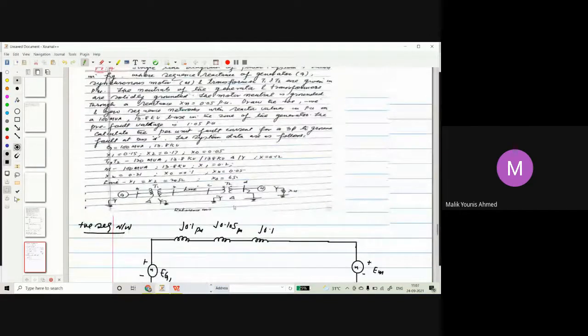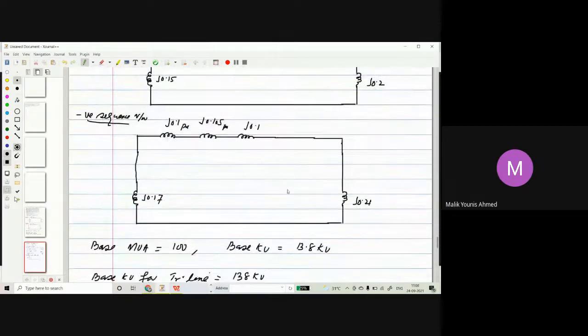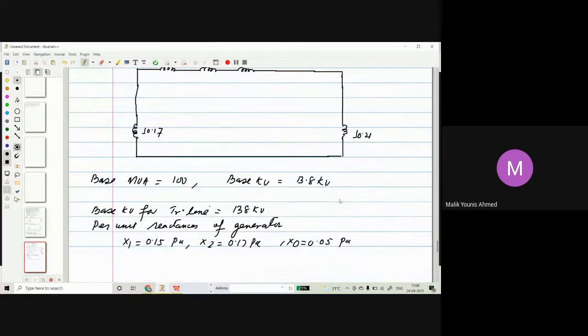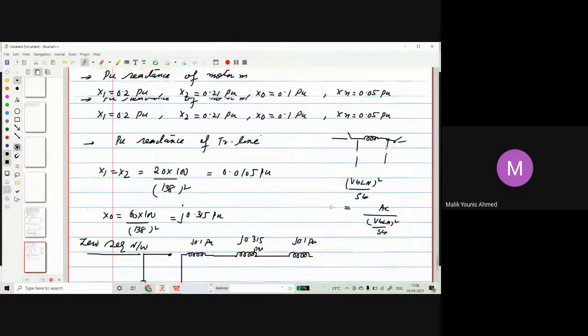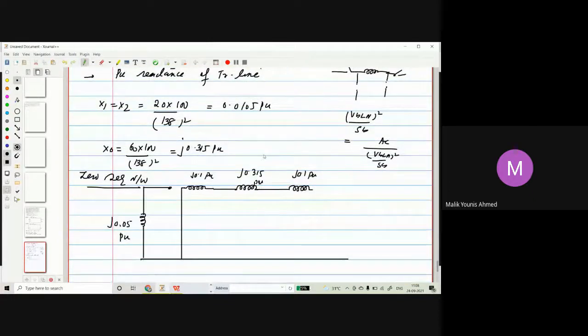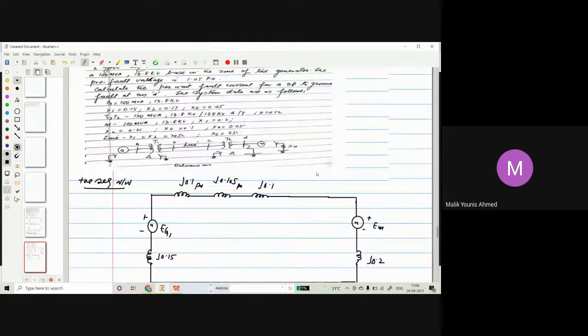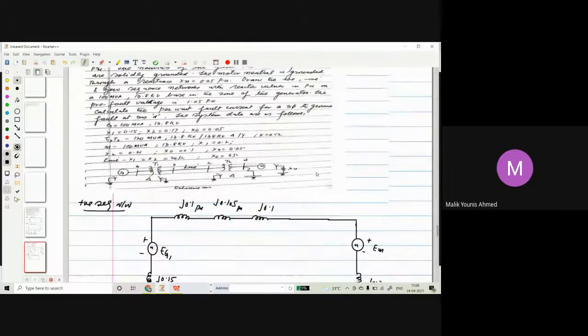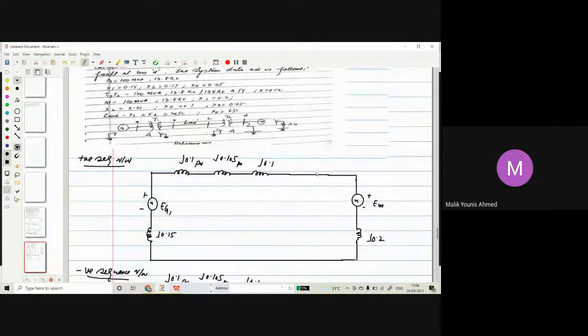Now have a look at the secondary side of the transformer. It is delta connected. That means on the secondary side the series switches will be opened, and definitely the shunt switches will be closed. So we have opened the series switch here and we can close the shunt switches here. After that, we have a generator that is reactance grounded.